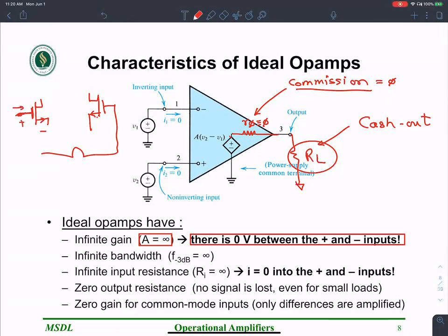It's the voltage between the gate and source that generates a current ID in the MOSFETs. So the assumption is that looking into the MOSFETs, you see the gate of a MOSFET over there, and you see another gate of a MOSFET over here, in which the gate is floating and there is no direct current flowing to that.